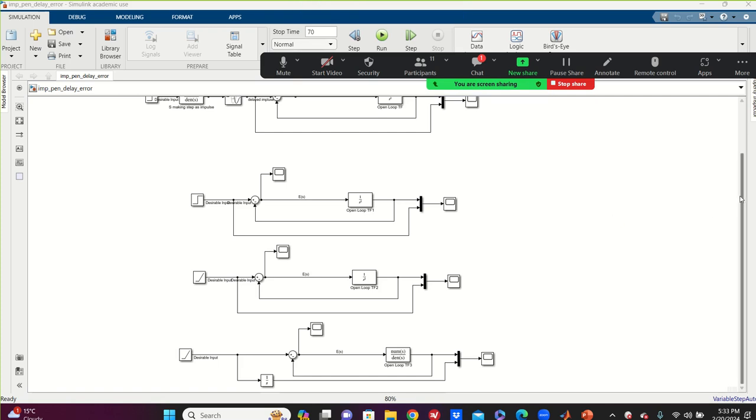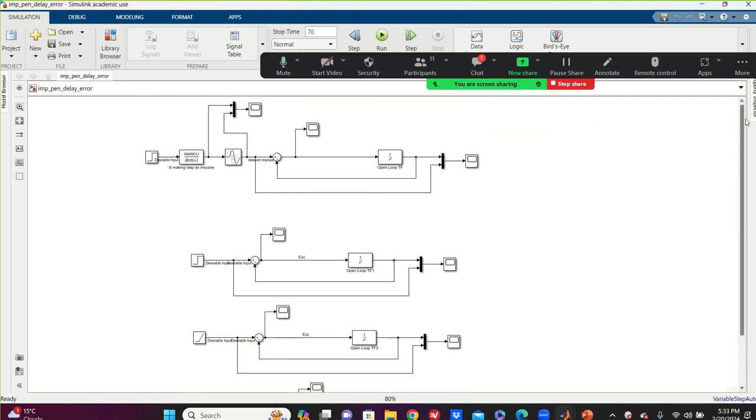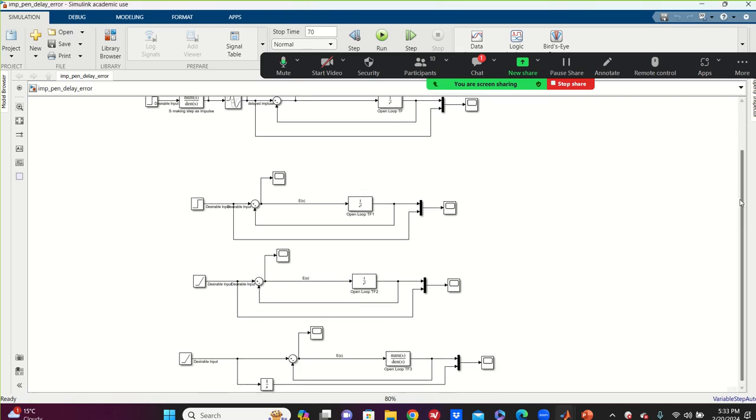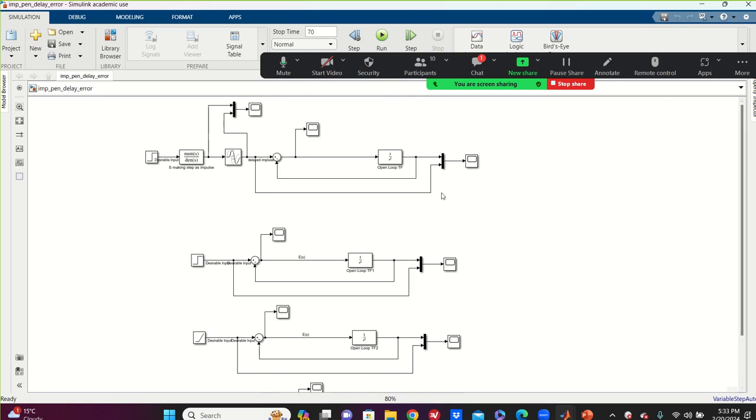Okay, in the last class, we plotted a Simulink together, and I did with you the closed-loop transfer function of a marginally stable system like a pendulum. We found G here, 1 over S squared, opened the transfer function, put in a unity feedback block diagram, and I taught you how to generate an impulse from the step by differentiating in frequency, which means S. And also I did a delay to show you what the effect of delay is.